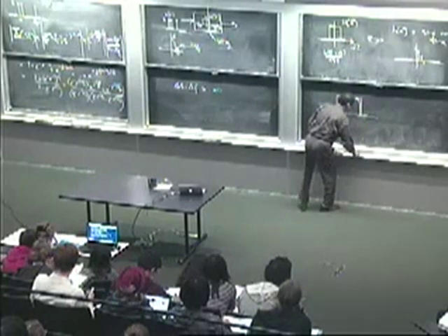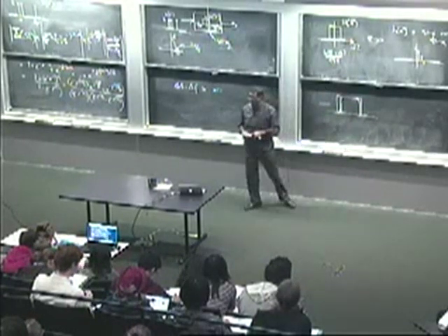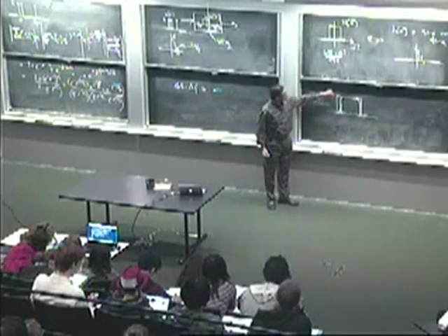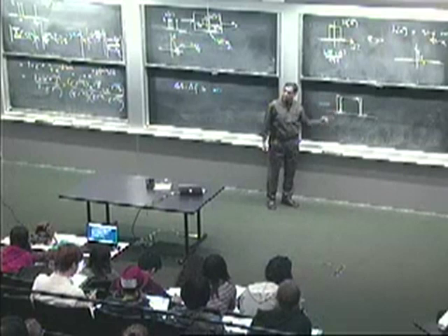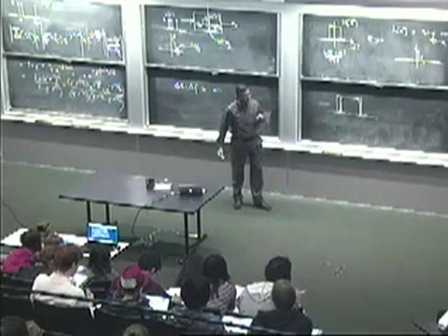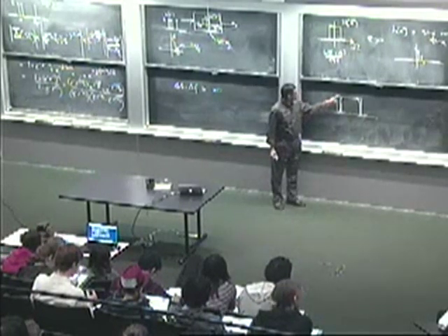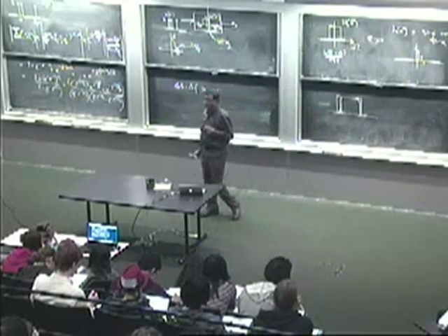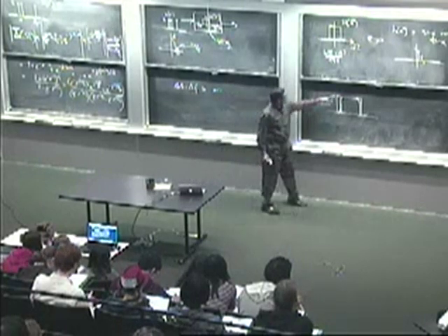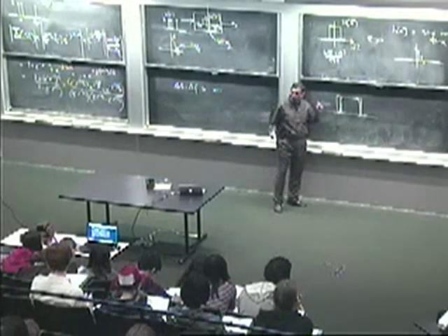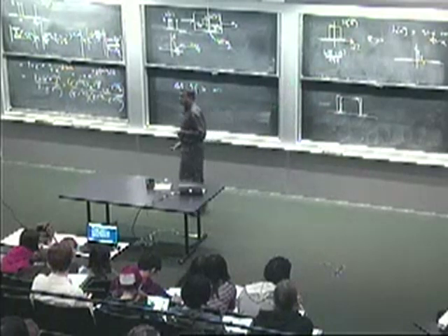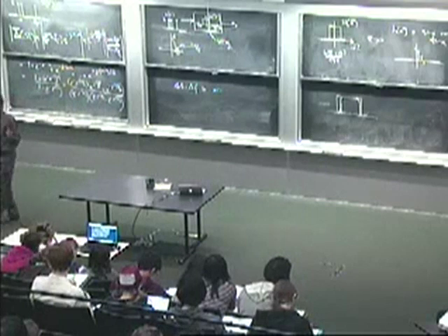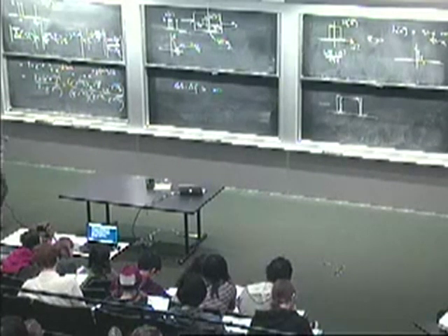This is actually something that's used quite a bit in applications. All right, so what have I done? I've removed the sharp edge and gotten a much rounded transition. In fact, if you're thinking of continuous functions, the original had a discontinuity, whereas here I've got to take two derivatives before I encounter a discontinuity, because the function itself and its slope at these ends are well matched. So I've got to differentiate twice before I get a discontinuity. So actually it has quite some smoothness to it. Smooth in time means more tightly concentrated in frequency.